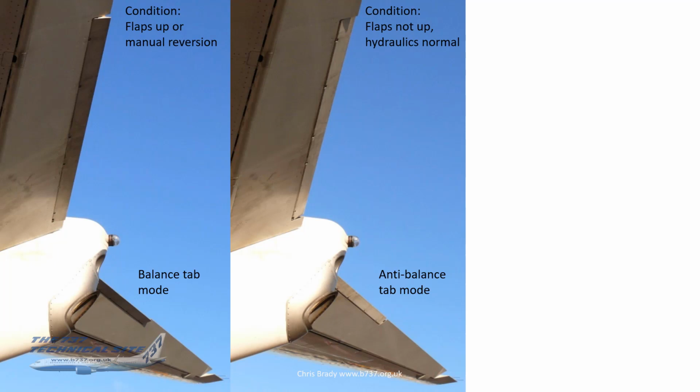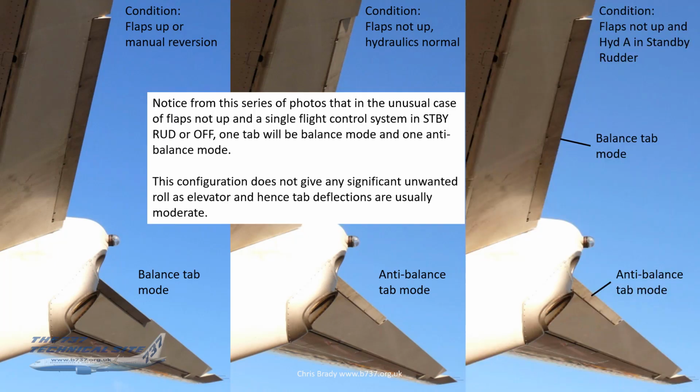Okay, here it is. What happened was, on the left-hand elevator, that tab went into balance tab mode because it said, hey, I'm in manual reversion, you want me in balance tab. But because the B system wasn't in standby rudder, that remained in anti-balance tab mode.